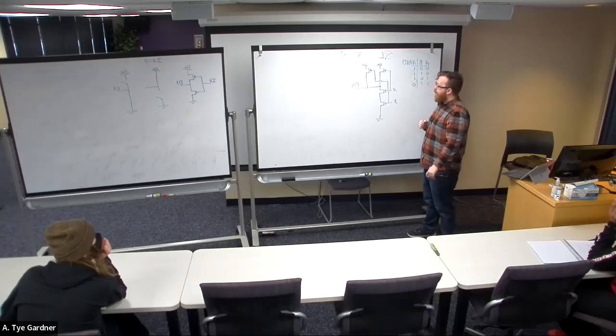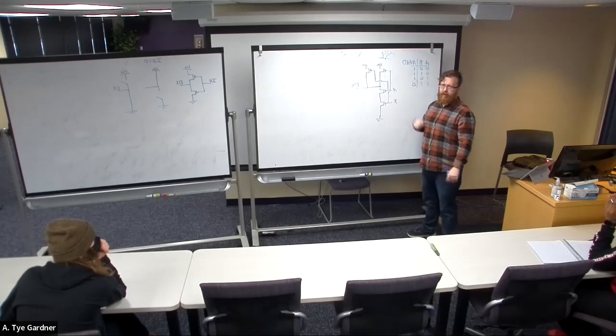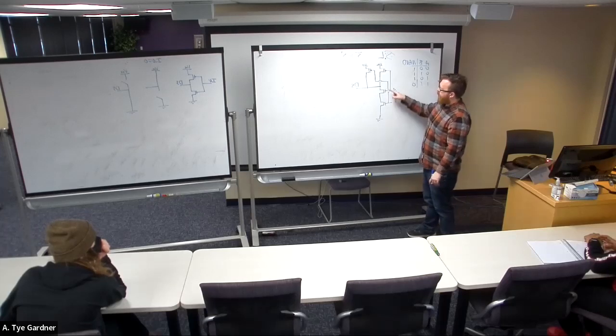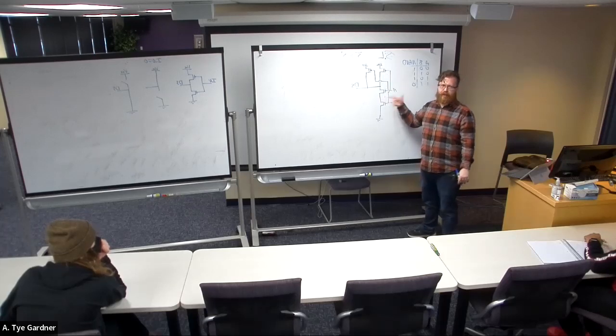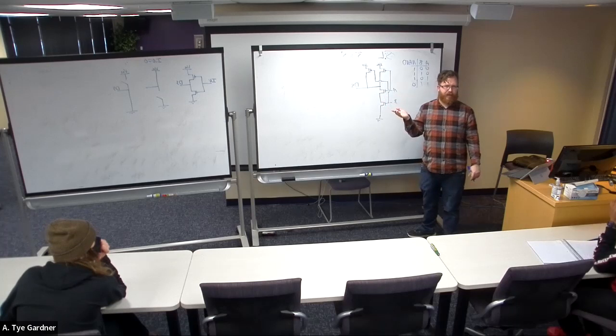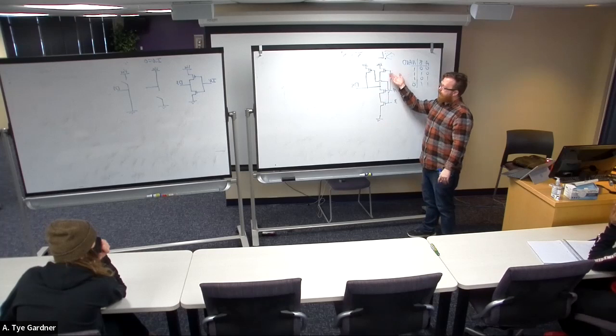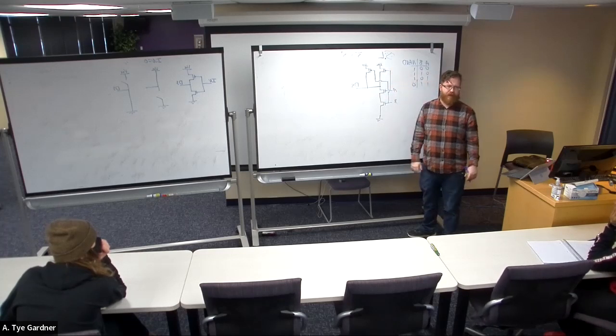Now, here's where we have to remember that PMOSs go up top, NMOSs go on bottom, because otherwise we're tempted to just turn those into NMOS and those into PMOS, and I have an AND gate. Because this is NAND, right? And we would like to do that, but we can't because the devices just wouldn't turn on at all. They just wouldn't work right. It'd be kind of chaotic behavior.